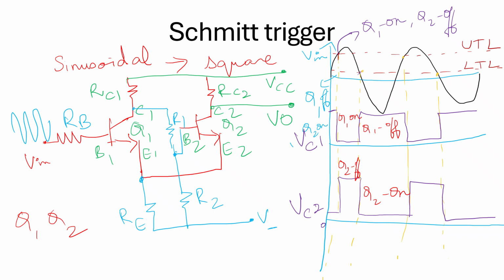As a result, the reverse bias of the transistor Q1 reduces and it starts to conduct more. Thus, the collector voltage of transistor Q1 drops, and the transistor Q2 is further driven into cutoff. This process will continue until transistor Q1 is driven into saturation and transistor Q2 is cut off.